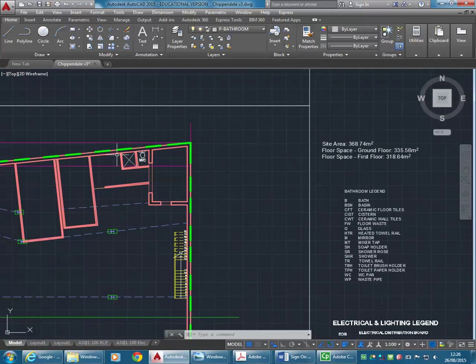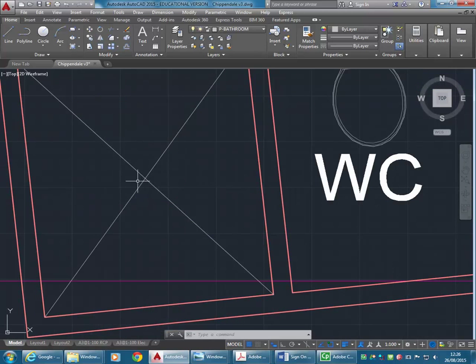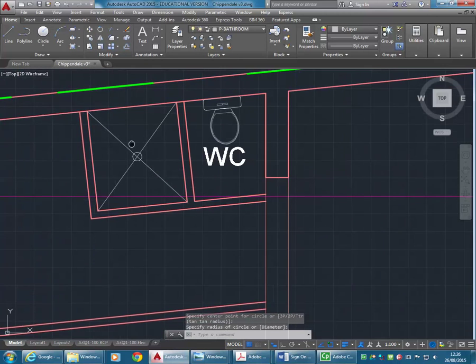So do you know what a floor waste symbol looks like? Yeah, that's right. Yeah, exactly. And because we've got a cross there, we don't really need to draw the cross that you'd normally have. So you could just have a circle there, and so just simply draw a circle. My eye is good enough here. That's fine.